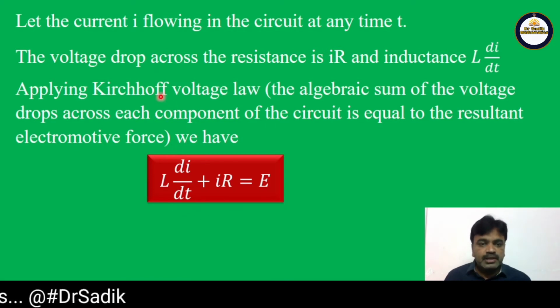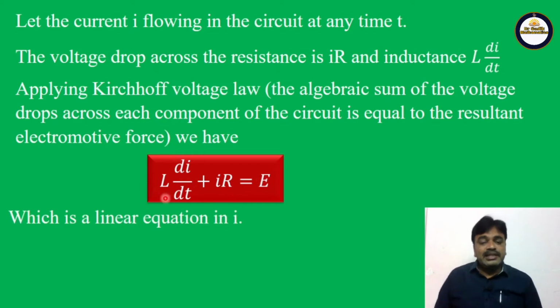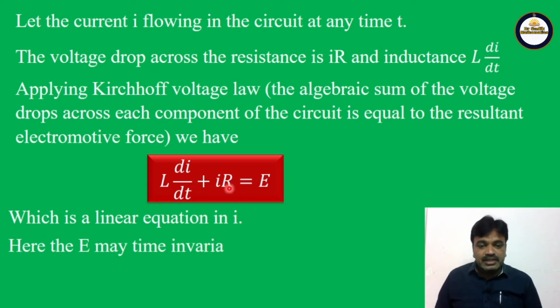So by applying Kirchhoff's law, what is the equation? L into di by dt plus IR is equal to E. This equation is very, very important, friends. It is a linear equation in I.